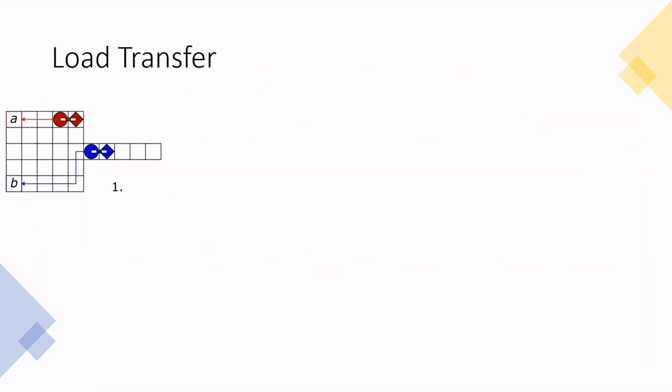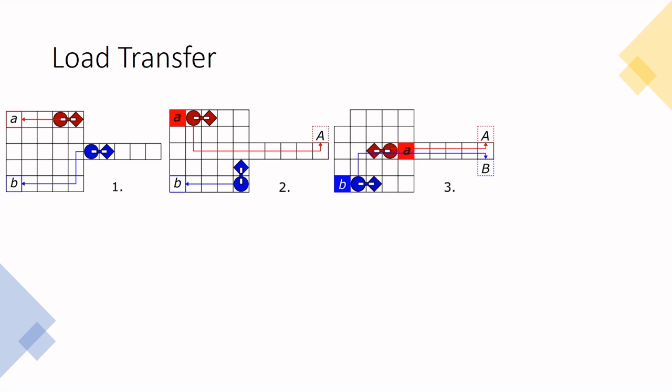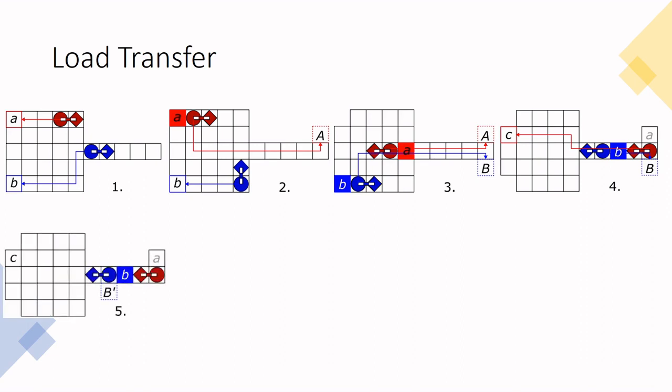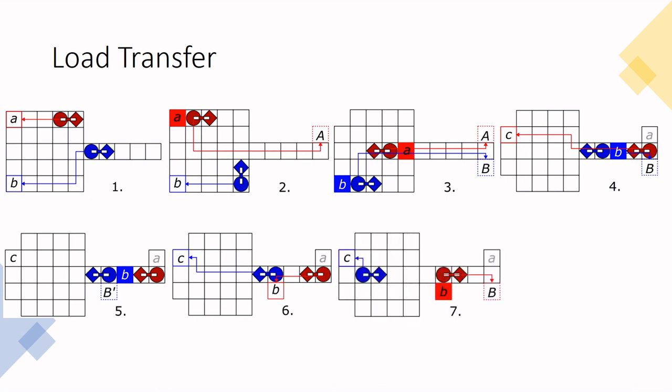Our second algorithm is based on load transferring. This allows one robot to transfer its carried tile to another robot. Transferring building materials between robots helps prevent collision and unnecessary waiting. Due to the design of the Billy bots, tiles cannot be physically exchanged between two robots. Instead, one Billy bot must find a place to drop their tile and then have another Billy come pick it up. Every iteration, the algorithm checks the combined distance cost to the next pickup and drop-off location pairs.